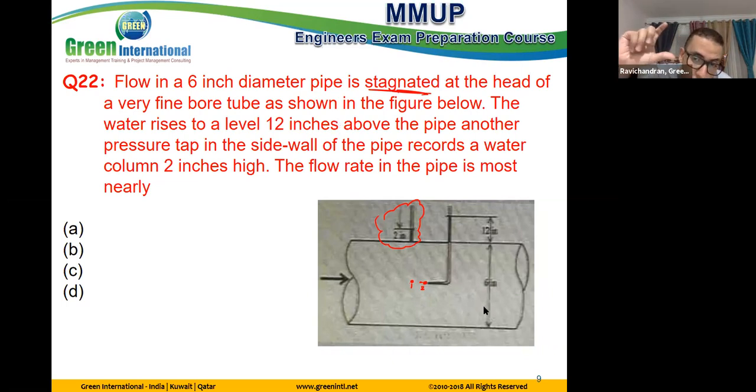What do you mean by 12-inch? Does this refer to the dynamic part? Not all. Why? Because actually this point has two energies, pressure energy and kinetic energy. So the dynamic part is converted to head. Where is the static part? It is also represented in head, same like the first one, 2-inch. So the 12-inch includes both the velocity head and the pressure head.